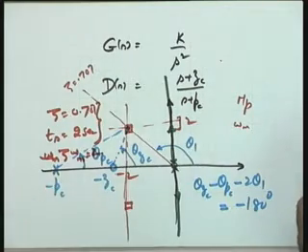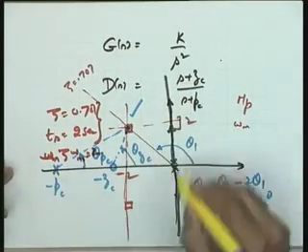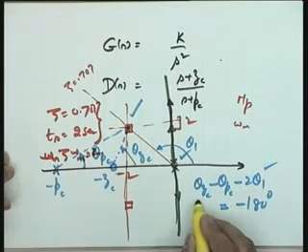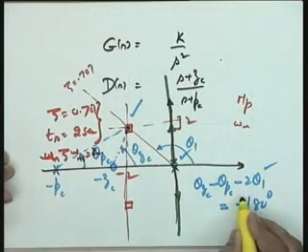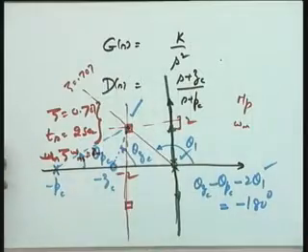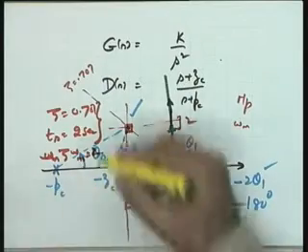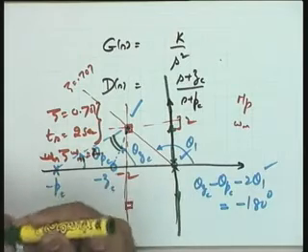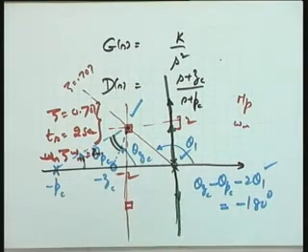And you know theta 1 because you know this location, you know the open loop poles, and hence you know theta 1, and therefore you know theta ZC minus theta PC. That is, you know what is the net angle which this pair should contribute. So it means the only requirement will be to place one of them at an appropriate location, and once you know the angle, the location of the pole will automatically follow if I am able to place the 0 at the appropriate location.